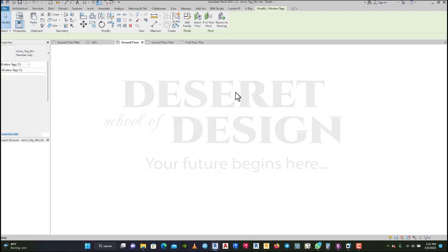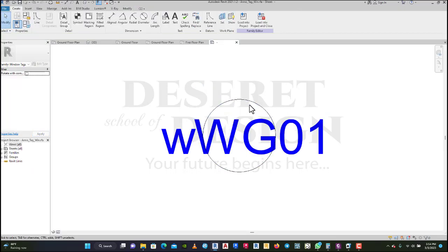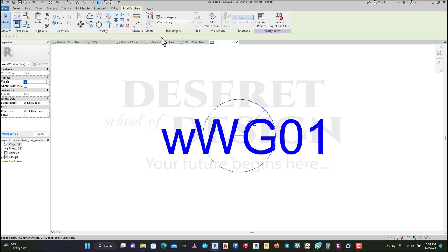Then this time around, now I didn't show you how to use a scale tool, so this is the way to use a scale tool. Now I want to scale up this circle. I want to make it big, so you have to use a scale tool. Now anything you want to scale up, want to reduce, you can use this. So select the circle, then under modify to this, after the arrow to this is the scale tool. Okay, so you select it.